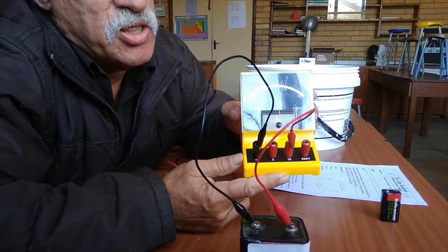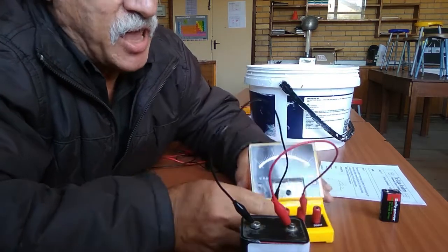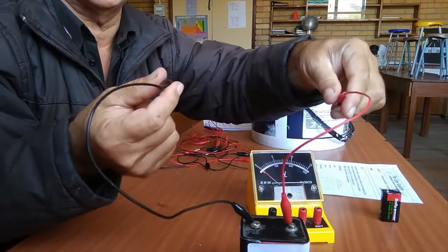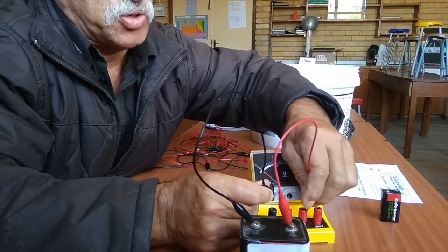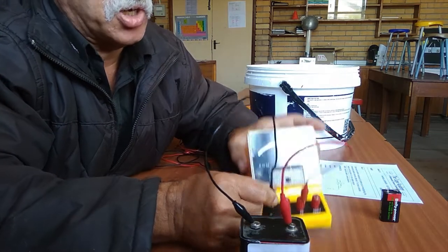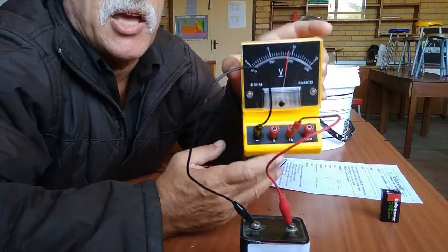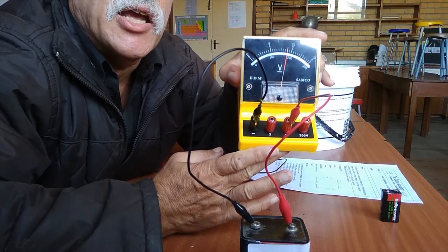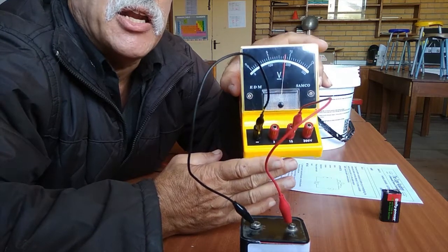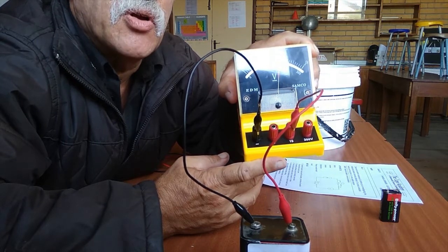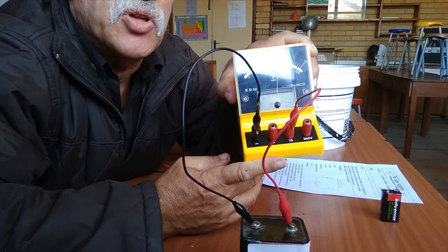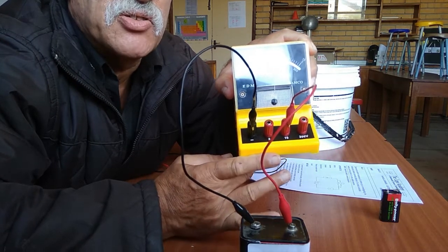It's almost like having air between these clips. It's not going to change the voltage or the EMF. So at the moment we are measuring the EMF as 8.9 volts. That's the maximum. You can't get any higher because of the chemicals in the battery. That's as much as they can push out. That is their top voltage, limited by the chemicals in the battery.